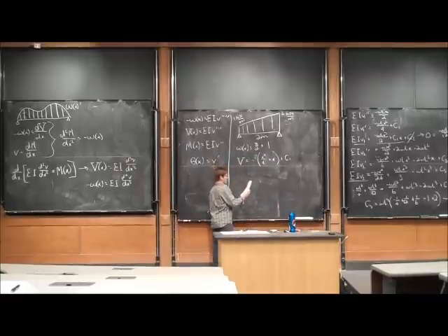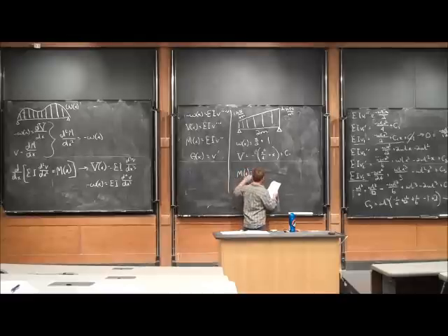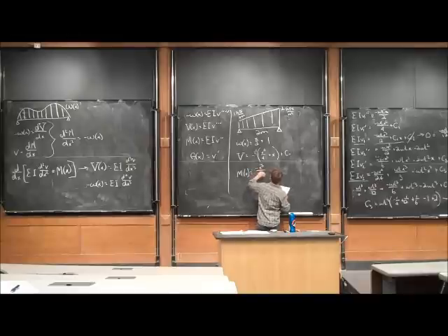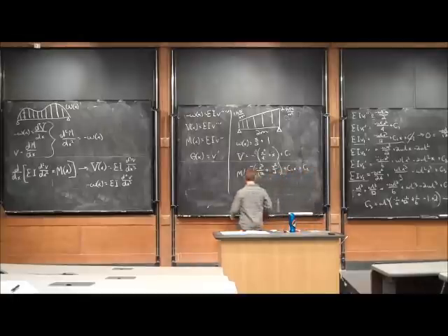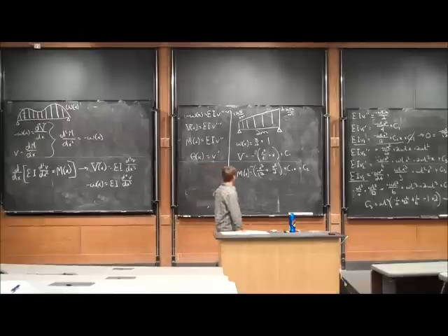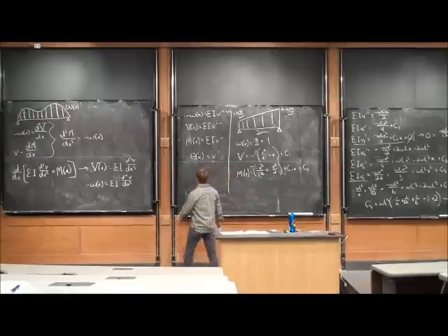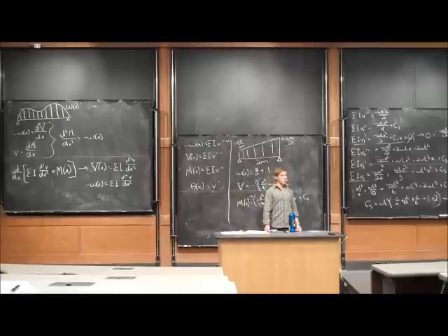I can integrate that again to get my moment equation. I get that my moment equation is going to be negative x cubed over 12 plus x squared over 2 plus c1x plus c2. I can then apply boundary conditions that we remembered from doing moment and shear diagrams. And what do we know about the moments at our endpoints on our pin beams? So pin beams can't exert a moment on the beam, so our internal moment goes to 0 at these locations.